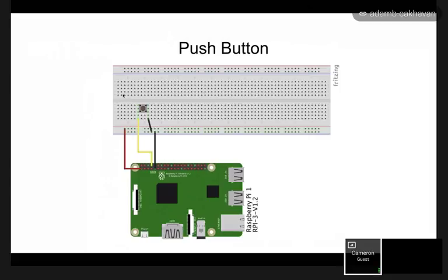We're going to look more at these little horizontal pins, and same concept goes for these ones. Every row of 5 pins, or every column, I should say, from this perspective, is connected in series. So this hole is connected, this hole is connected, this hole all the way down, but it's not connected to the hole across. And this is really useful because now you can cascade different electronics, like this little push button here that we have connected in this column and this column.